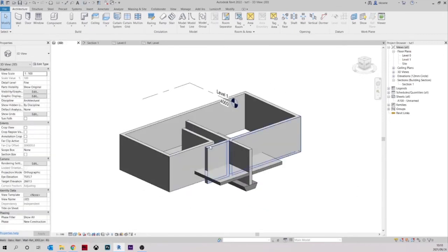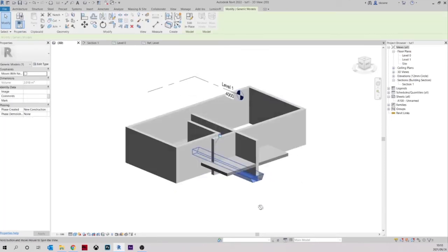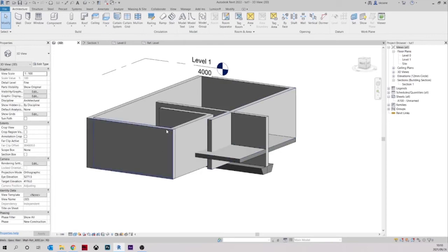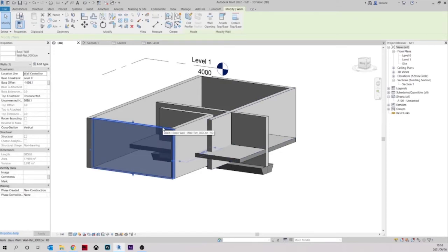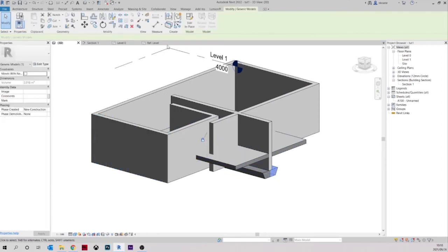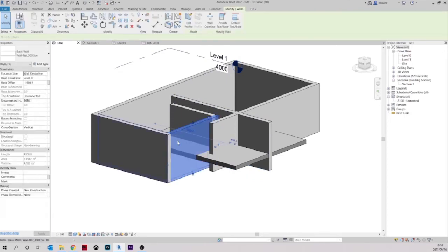Remember, we want that to go on all of these walls. So what you can do, if you don't like this tedious option, you can either delete or keep it just to match. So let's first of all remove this one. Delete, remove, delete. We're going to select the wall and we're going to go to edit type,